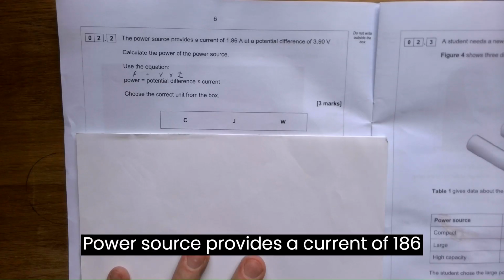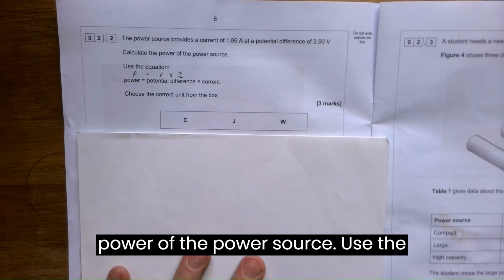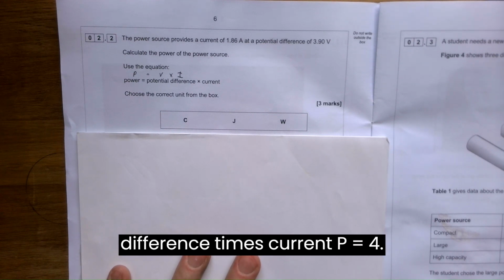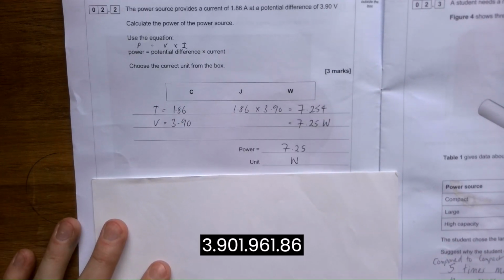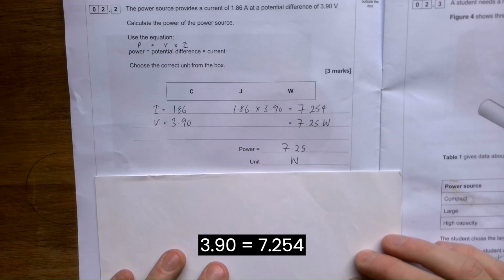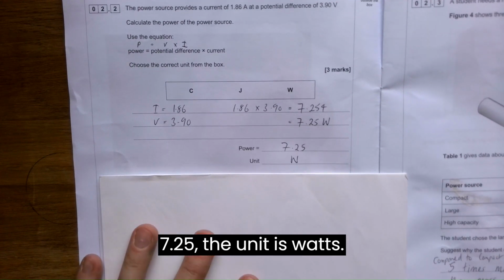A power source provides a current of 1.86 amps at a potential difference of 3.90 volts. Calculate the power of the power source. Use the equation power equals potential difference times current. P equals IV. Choose the correct unit from the box. I is 1.86, V is 3.90. 1.86 times 3.90 equals 7.254. To three significant figures, 7.25 watts. The power is 7.25, the unit is watts.